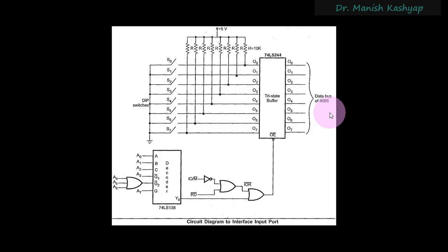On the address lines, instead of taking from A0 to A7, you could also use A8 to A15, because there the address will be available all the time. Since they have taken A0 to A7, their circuit depends on the address latch enable signal, so that when you try to transfer data, this combination will become data and this circuit will be automatically deactivated. So both ways can be used, and that is how you take inputs from the input port.